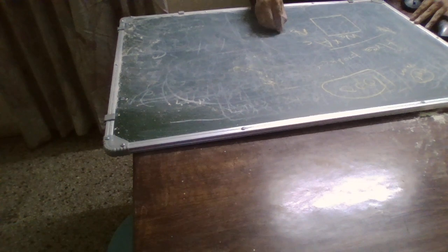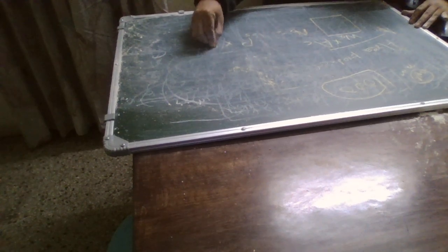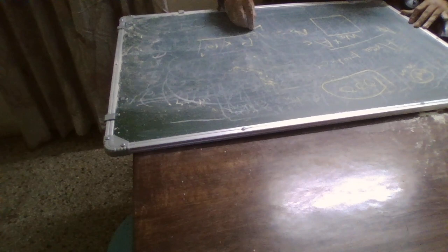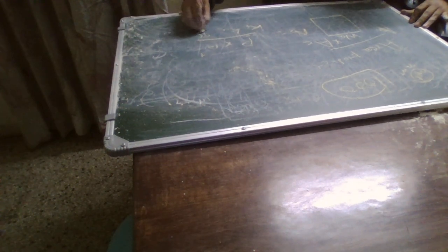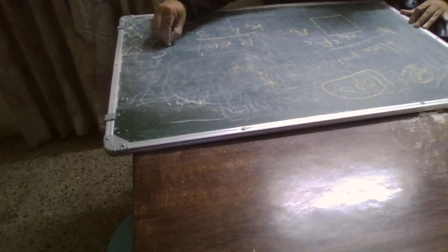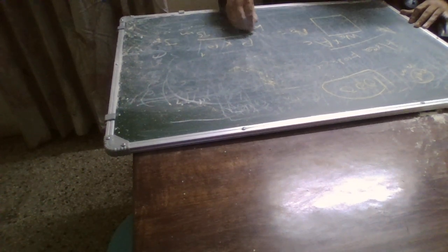This area product is equal to power times 10 raised to power 4, divided by Kf, Ku, Bm, J and F. Kf is basically a waveform coefficient, depending on whether you are having a sine wave or a square wave.